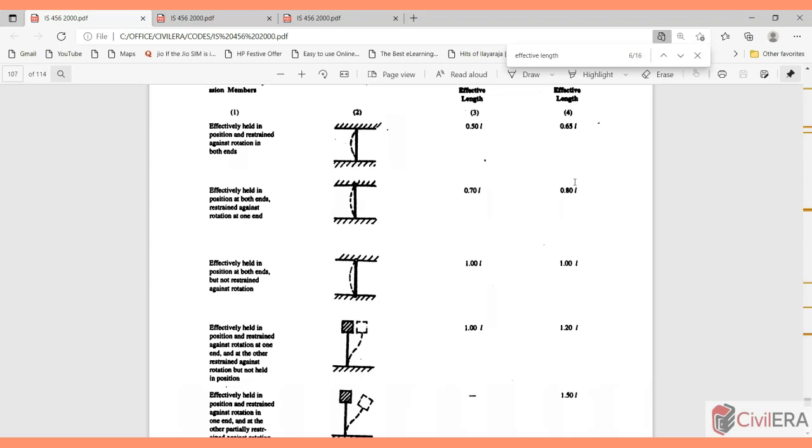No, you are not doing that. You are leaving the stiffness to play. You are assuming that the software will develop the necessary fixity based on the stiffness. You are considering that, and that's a right consideration. The stiffness plays, and then you get your fixity and your inertia or your stiffness in the right way, and then get the load distributions. That's the right thing to do. You are not pinning or fixing the joints.